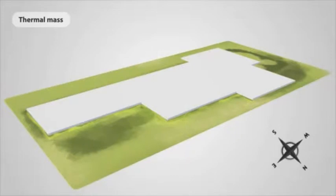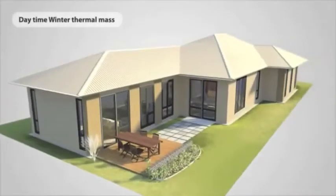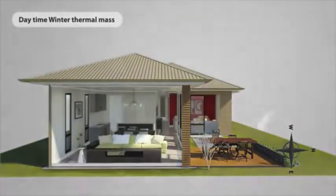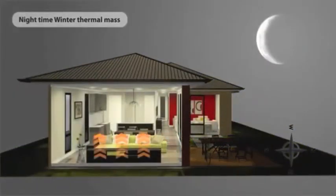Thermal mass has the ability to store and release heat. This can be heavyweight materials like brick or concrete, but they need to be on the interior to work as thermal mass. The advantage to thermal mass is that it moderates the temperature within the home in both winter and summer. The winter sun shines in the house onto the thermal mass, which absorbs the heat of the sunlight. At night, the heat from the thermal mass gets released into the home and helps to maintain the temperature, requiring less artificial heating.